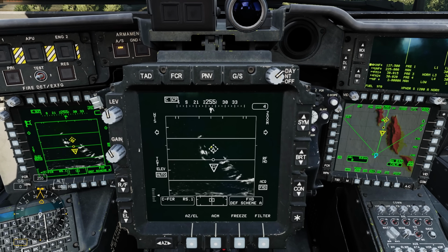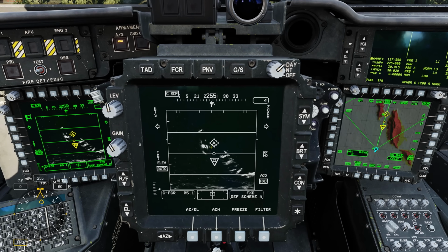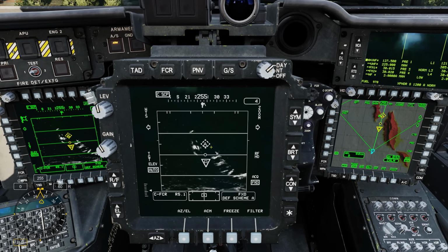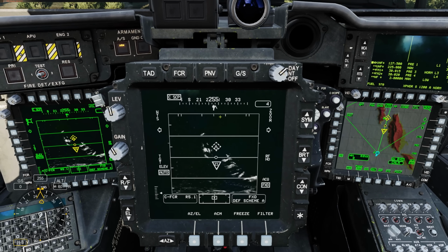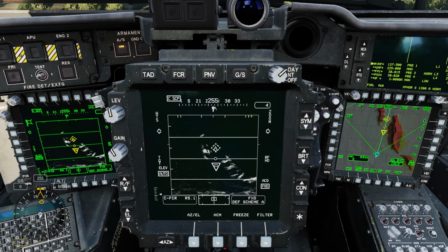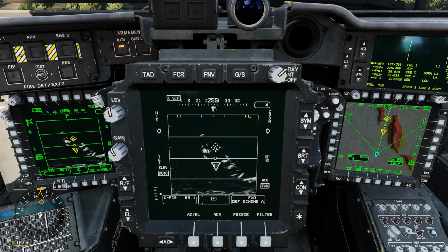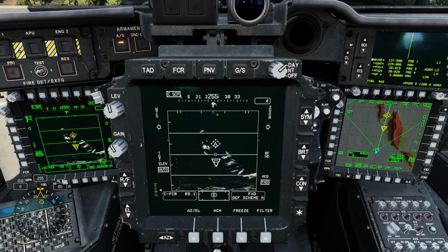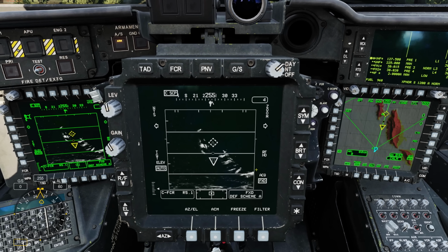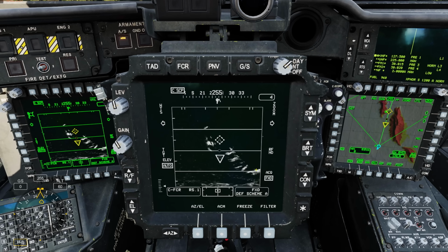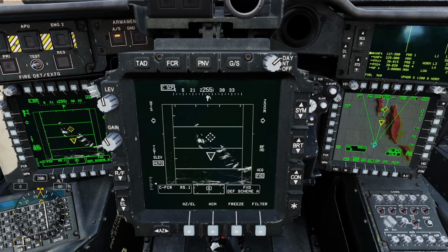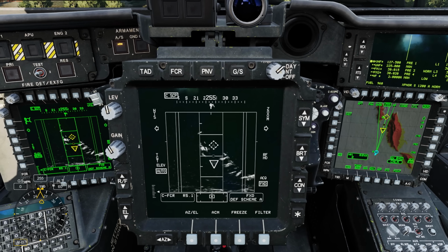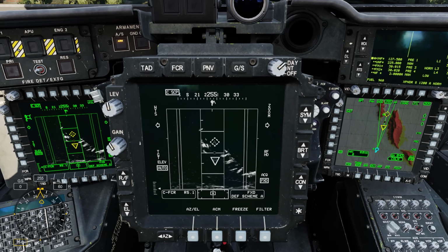And when you make a scan, it's going to stay stabilized on that azimuth. So as you maneuver the aircraft, it's not going to follow the scan with you. Also, we have markers. The outside marker here is the medium azimuth. Then we have narrow, and then we have zoom. And assuming that you are not actively scanning, you can switch those: medium, narrow, and zoom. And as you might imagine, the more narrow the scan, the faster the updates.